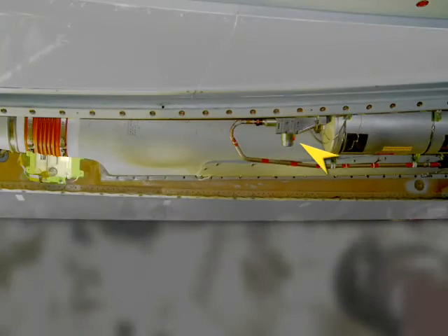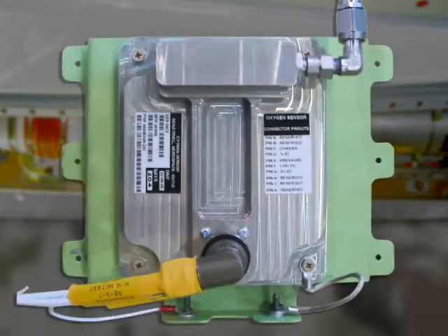You can't see it here, but a line from the back of the high flow valve goes to the oxygen sensor. The oxygen, or O2 sensor, is forward of the ASM assembly, inboard of the ram air duct. The O2 sensor samples the amount of oxygen in the NEA and sends a signal to the NGS controller for monitoring and indication. We'll talk more about that later.